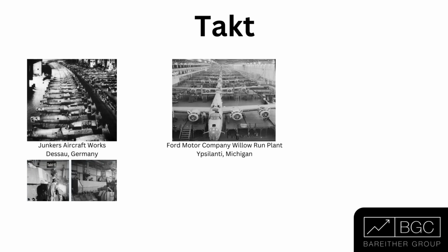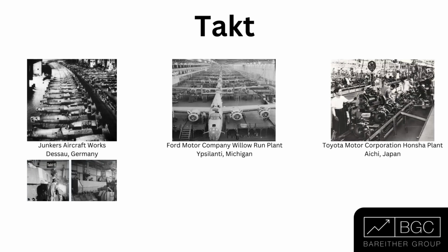Now, there's a selection of other tools and concepts that enabled this pacing, but it had to synchronize the assembly and subassembly lines to some pace or interval that we refer to today as Takt. Now, Toyota developed this principle when they were architecting the Toyota production system post-World War II recovery. So a great concept that now Toyota brings into the fold and really perfects so that through modernizing their production control, they would increase production capacity without increasing employees to do that. And this concept took on the standard that we recognize today in terms of takt time.